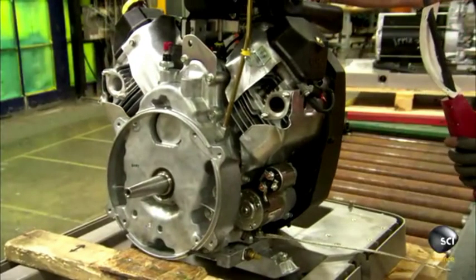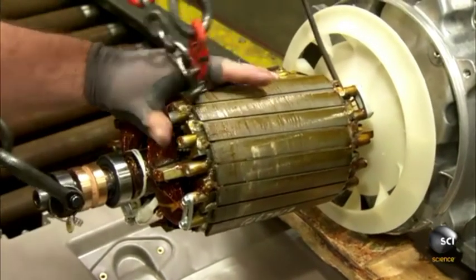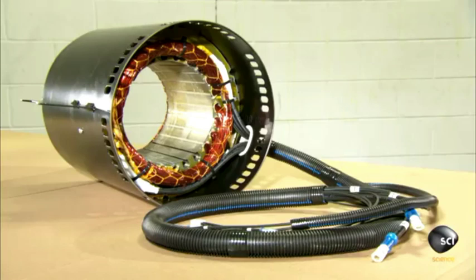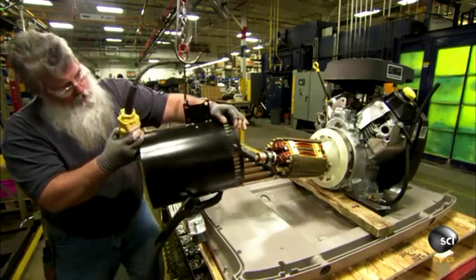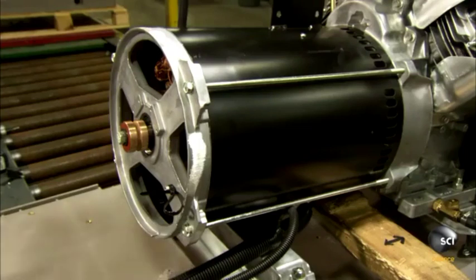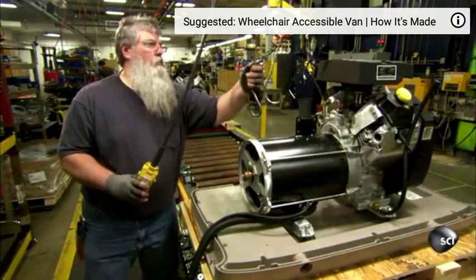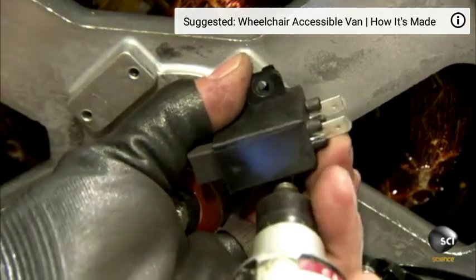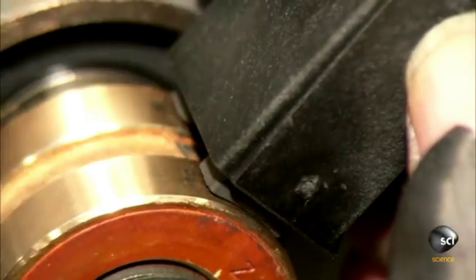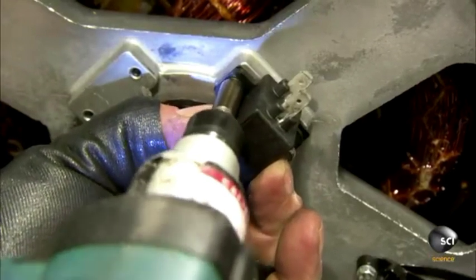Using a lift, the technician lowers the engine into position. He joins the rotor shaft to the engine crankshaft. Next up is the stator. The technician slides the stator onto the rotor. He anchors the stator and rotor to the generator base. He attaches a motorized carbon brush to copper rings on the rotor shaft. The brush will collect electricity from the shaft and transfer it to the generator controller.